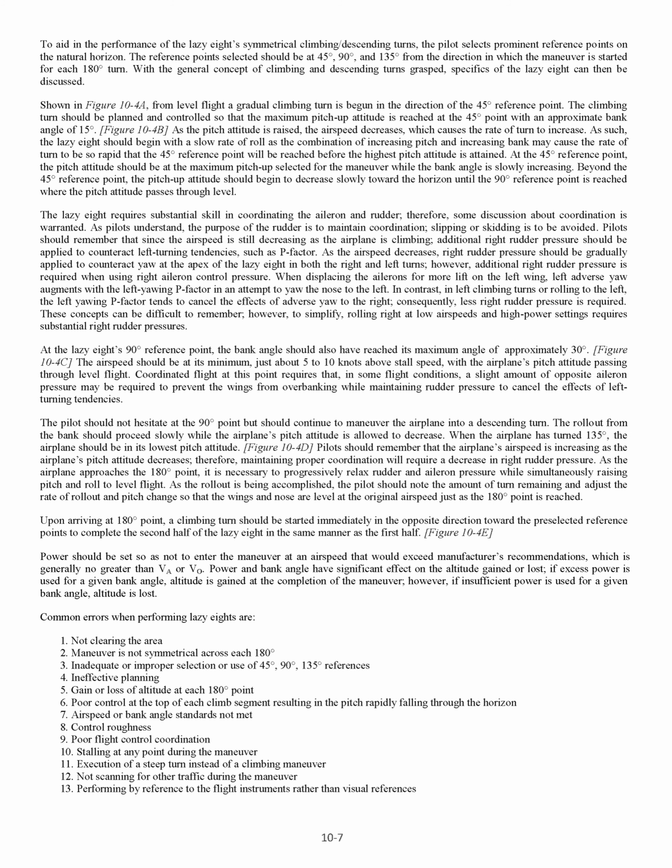These concepts can be difficult to remember, however, to simplify, rolling right at low airspeeds and high power settings requires substantial right rudder pressures. At the Lazy 8's 90 degrees reference point, the bank angle should also have reached its maximum angle of approximately 30 degrees. Figure 10.4c, the airspeed should be at its minimum, just about 5 to 10 knots above stall speed, with the airplane's pitch attitude passing through level flight.